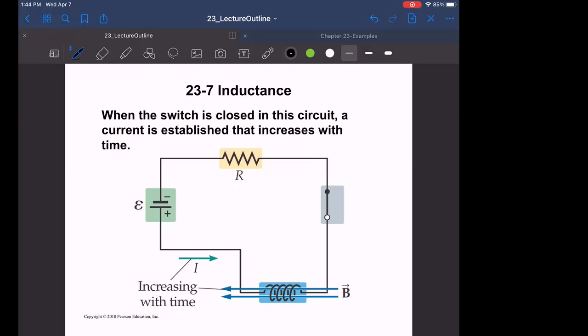What happens when you first turn on current through a capacitor? That's right, it acts like a short. Initially, when you first turn on current through a capacitor, it acts like there's nothing on it because there's no charge on it and all the current can just flow with no resistance. Then as the charge builds up on there, it gets harder and harder to push more charge on there and the resistance goes up.